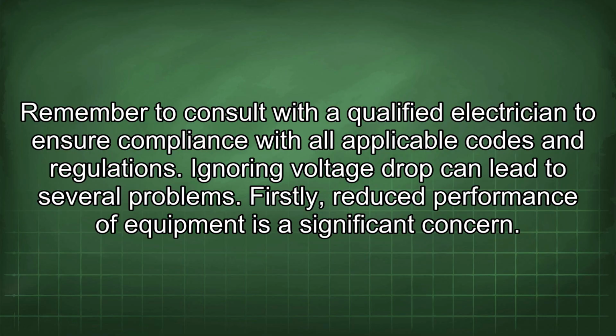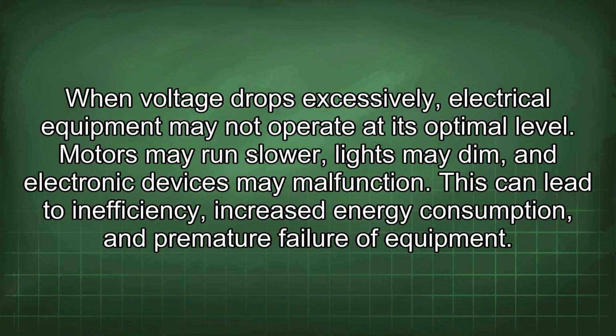Ignoring voltage drop can lead to several problems. Firstly, reduced performance of equipment is a significant concern. When voltage drops excessively, electrical equipment may not operate at its optimal level. Motors may run slower, lights may dim, and electronic devices may malfunction. This can lead to inefficiency, increased energy consumption, and premature failure of equipment.